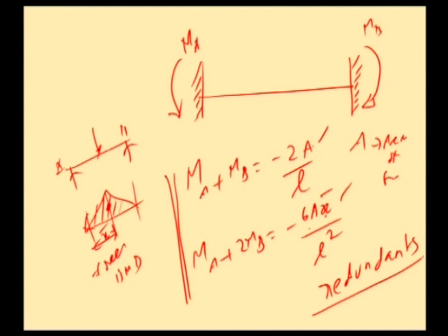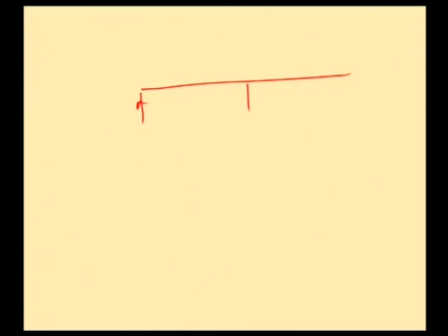And then we have the continuous beam. As I said, for a continuous beam of this type, the additional unknown will be the moment at B. Once the moment at B has been found, then we can easily find the reactions at supports using equations of equilibrium, and then we can proceed in finding shear force and bending moment. So, how do we find this M B?